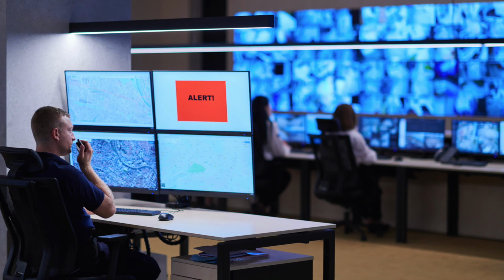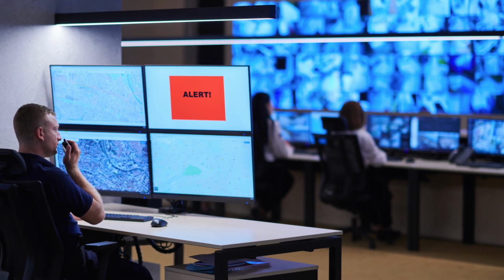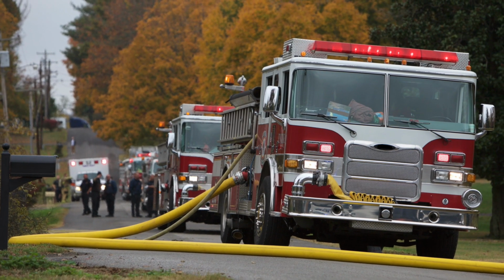If an alarm goes off in a building on an addressable system, let's say an electrical closet on the 3rd floor, the display will be that smoke detector goes into alarm. It will come to the fire alarm panel stating 3rd floor electrical closet. That also will then send a signal to the central station. The central station will relay that over to the fire department that, hey, 3rd floor electrical closet is in alarm. So now they can prepare themselves because they know exactly where the fire is at, especially in an electrical room. You use different agents to put that fire out.